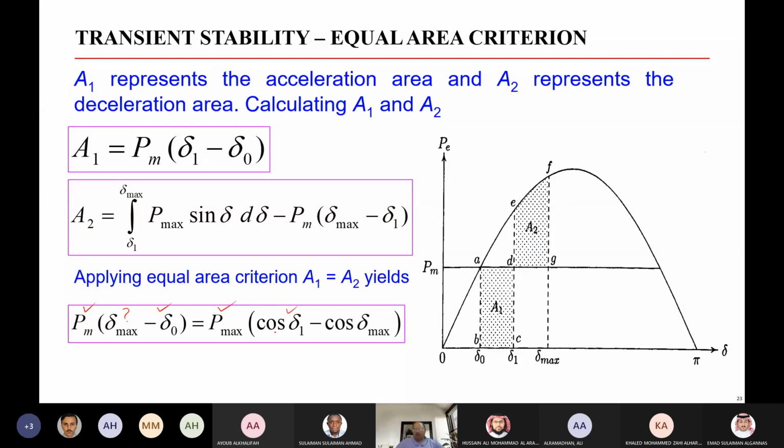And of course, when you clear the fault, you can express this either in terms of time or in terms of angle. And you can say we clear the fault at the angle equal to 70 degrees, delta 1 equal to 70 degrees.